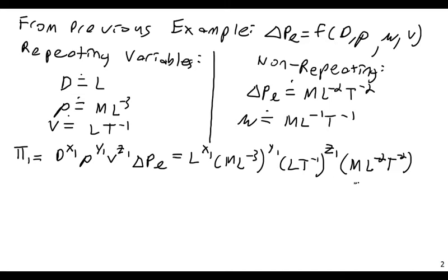Now, once all of this multiplies out, it must come to L0 M0 T0, or just 1. So you can start to see the origins of our linear equations. If I distribute these down, I can start getting some equations and relationships that will allow me to determine all of my other powers. So let's work with the pi one first. I'll work all the way through the pi one, and then I'll go back to the pi 2.